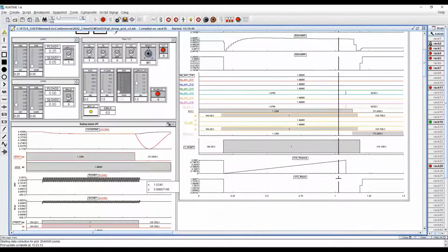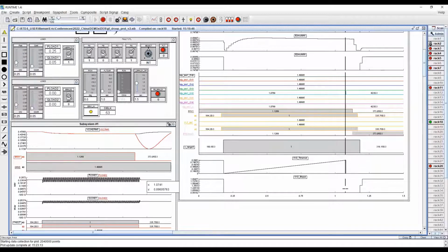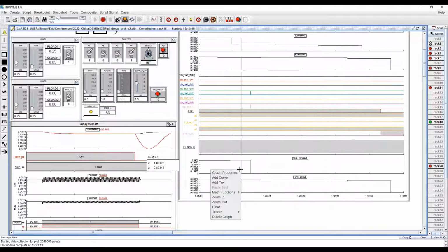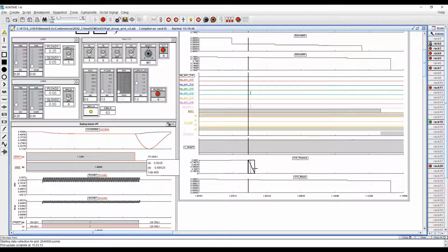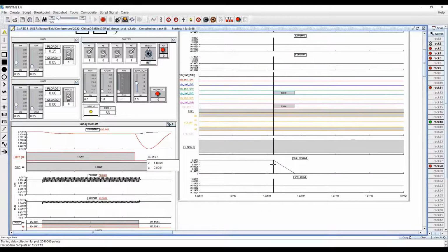This time the duration in which the voltage resided in the specified region was greater than the minimum time requirement for ride-through. Therefore, a trip was asserted. We can see here this is 0.8961, 0.8960.